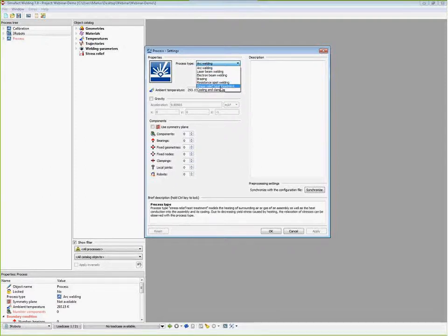We have the stress relief heat treatment module, which is simply an oven, and we also have this special thing called cooling clamping, which could be an intermediate simulation between two welding sessions, where you have to change certain clamping conditions, or even you want to unclamp your already welded structure. And in this condition, you don't have to set up weld lines and something like this.